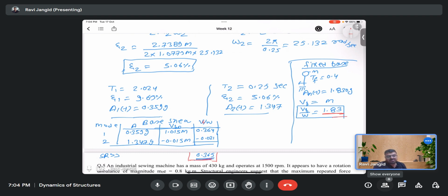So can you get it? How much difference is there in the shear between the base isolated building and the fixed base building? In percentage, the fixed base building is around 180%, or about 5 times the base shear. So using that isolator, how much base shear reduction is there in the building?